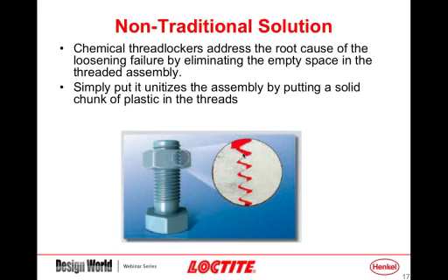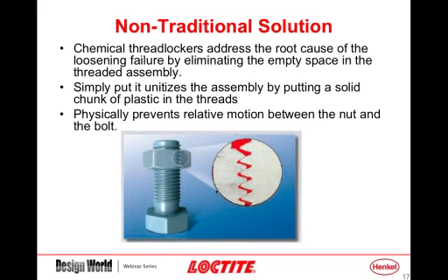So it actually does bond to the lateral surfaces of the threads and further increases the frictional force of trying to disassemble the fastener. And so it's a totally different approach, and as a different approach, it addresses the loosening at the root.